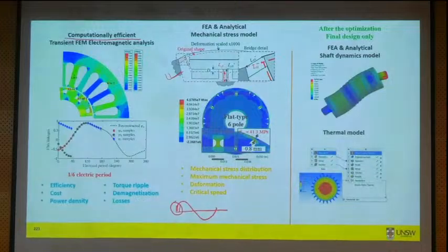A few things were done only for the selected, refined designs, not for all the designs. So one was that in high speed, you also need to check whether there is any resonance in your shaft. That was done outside. Similarly, thermal was done outside for our case.